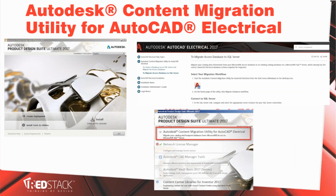So you can't find this shortcut icon anywhere. What you have to do is run the installation again and then choose Install Tools and Utilities. You've got to choose this option. Once you click that, the dialog box pops up, and the first entry here says Autodesk Content Migration Utility for AutoCAD Electrical. So make sure that is ticked. You don't need the other software. For example, if you don't use network license or CAD manager tools, or you're not configuring roles, you don't have to tick all the other options. So just tick the first one and untick all the rest. It only takes a few seconds to install, a very small program. Once you install it, it will come up with the icon on your desktop and your startup menu.